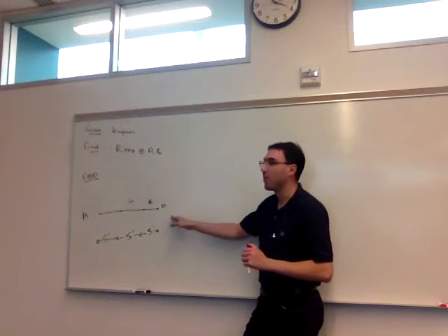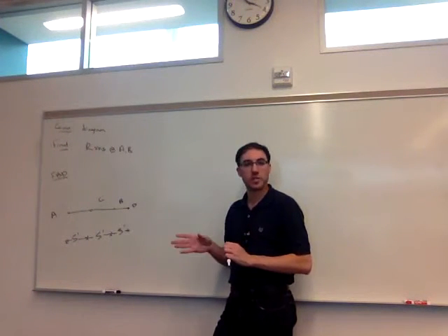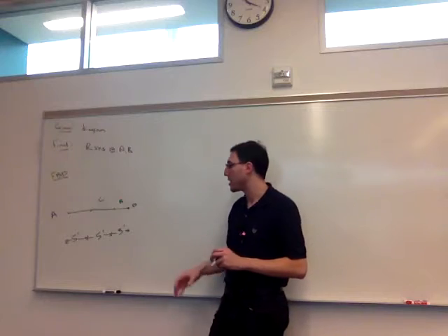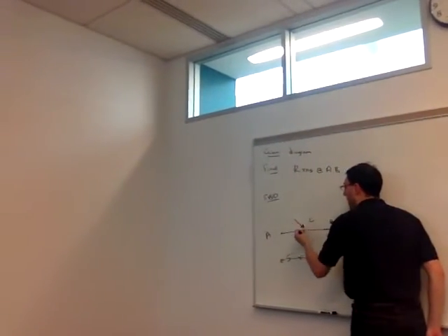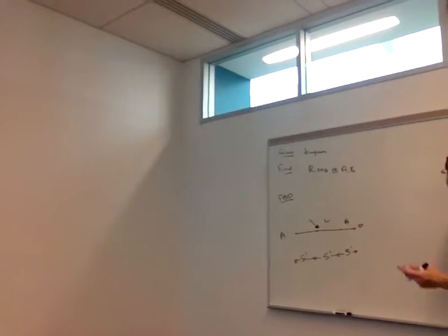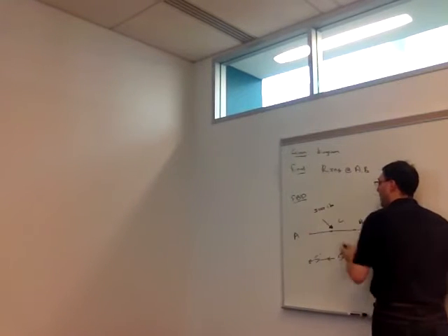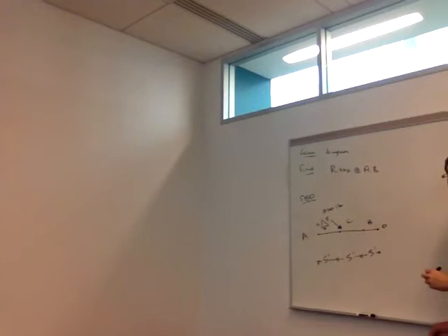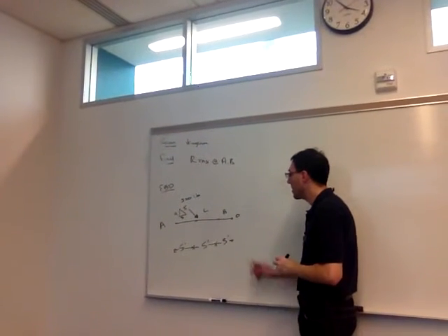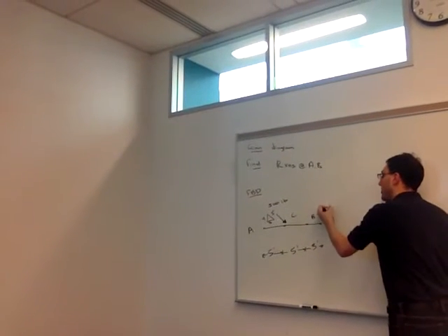So the next thing I want to do is look back at my original diagram. I want to copy exactly the applied forces, because those will come with it. So any applied force that's on the object that I chose comes along for the ride. So I have this 500-pound force acting on my beam at a 3-4-5 ratio triangle. And I have this applied couple acting at what I call D, 600 pound-feet.